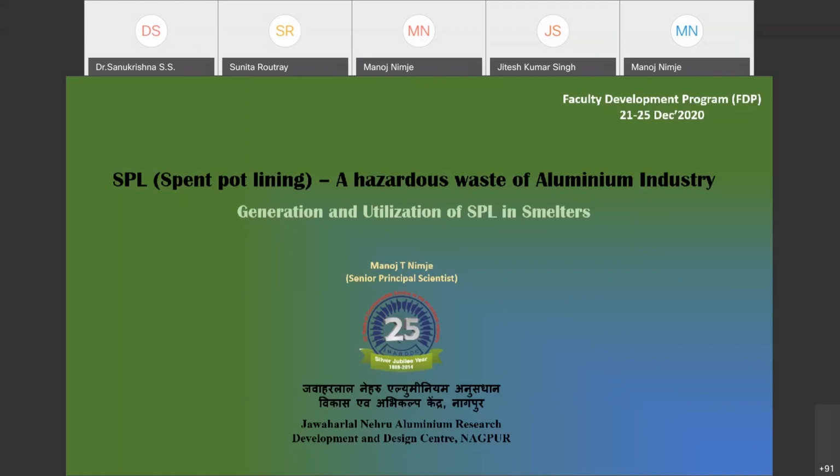The basic idea of this presentation is to give you information about spent pot lining, or in short, we call SPL. SPL is a hazardous solid waste generated in aluminum industry during the production of metal aluminum by electrolysis process.